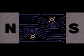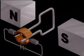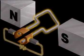As the armature rotates, it becomes perpendicular to the magnetic field and enters the neutral plane where the interaction of the magnetic field is balanced. Here, there is no longer any push on the armature. At this point, the brushes cut current to the armature. However, because of the rotating motion, momentum carries the armature into the opposite field.